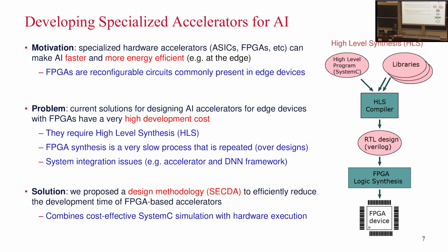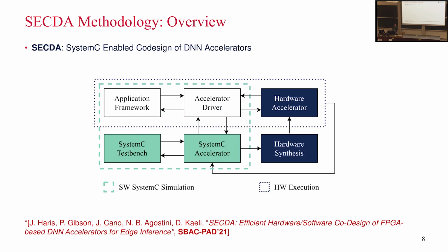So we realized these two things, and in order to solve that, we propose a design methodology called SECT to efficiently develop FPGA-based accelerators. Basically, instead of doing synthesis all the time, we combine quick, fast simulation with a few iterations of synthesis on the real hardware. Clear idea, more or less? Fine. Let me tell you a little more about this methodology called SECT, SystemC-Enabled Co-design of Edge AI Accelerators.